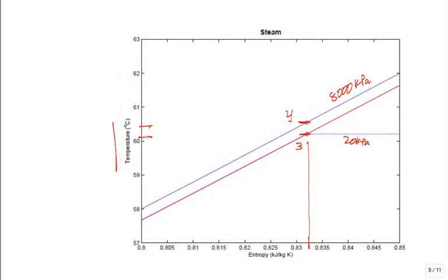Now, if you had some irreversibilities, well, then the friction in the pump, and then you say, does the pump heat up and then heat up the air, or does the pump heat up and then heat up the water that goes through the pump? That's a question you can deal with later. But for the perfect pump, it really comes out so slightly hotter. It's insignificantly warmer, okay?